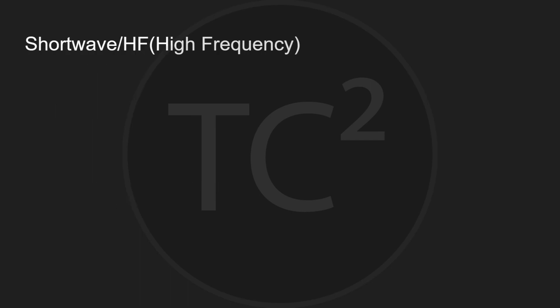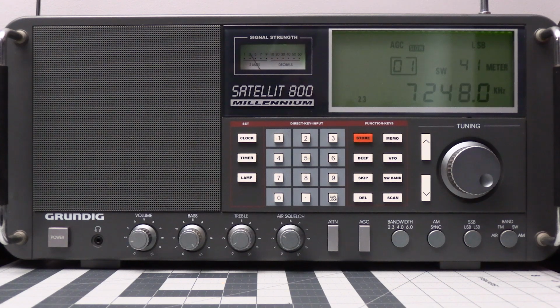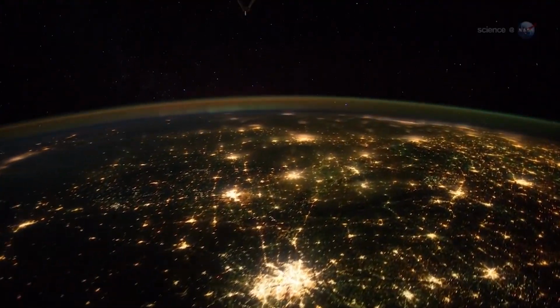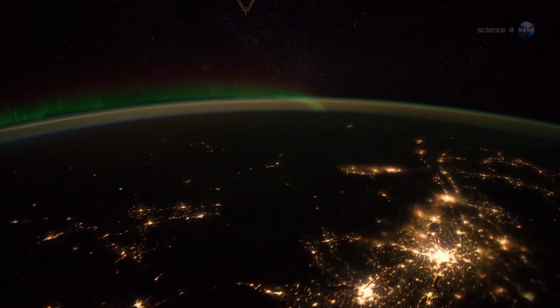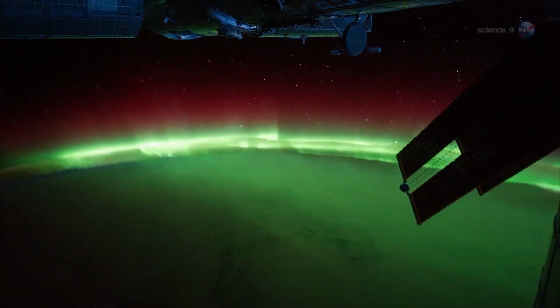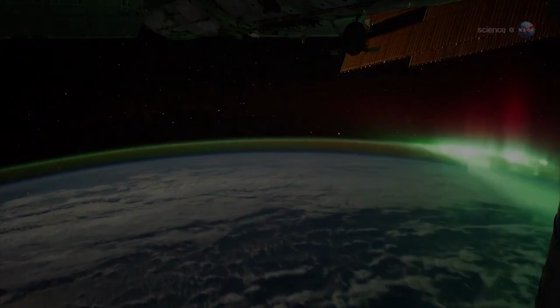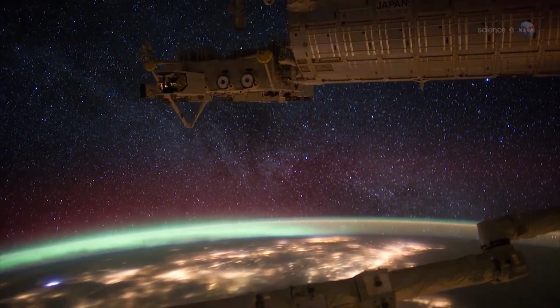The next type of radio on the list of receive-only radios are going to be shortwave or HF radios, high frequency radios. These radios cover the lower frequencies from around 1 megahertz, actually lower than 1 megahertz typically, to 30 megahertz. And what's neat about these frequencies is the signals can bounce off the ionosphere and back down to Earth. And this bouncing off of the ionosphere allows signals to travel very long distances, often multiple countries away. Communications on frequencies above HF, like in VHF or UHF, are not able to bounce off the ionosphere, so they're limited to line of sight only.